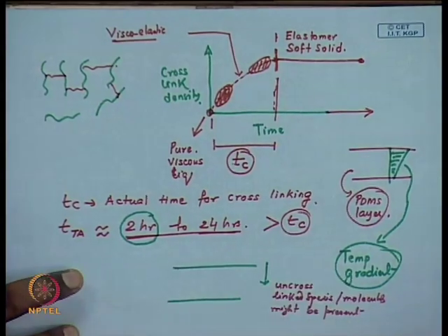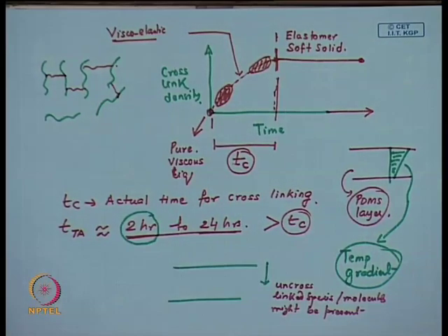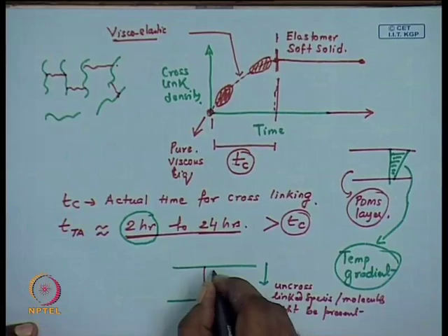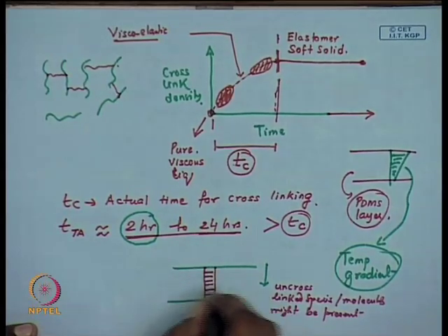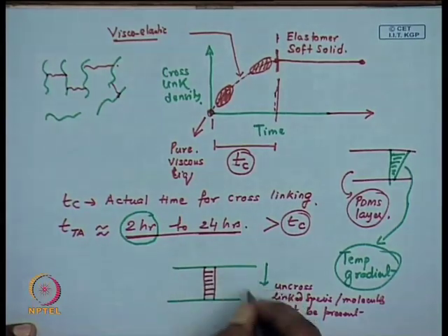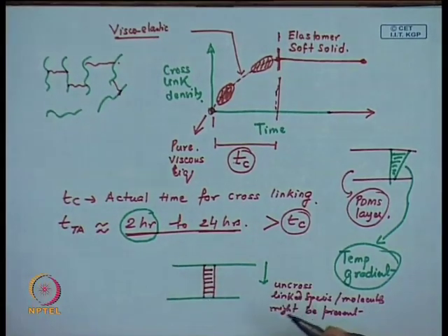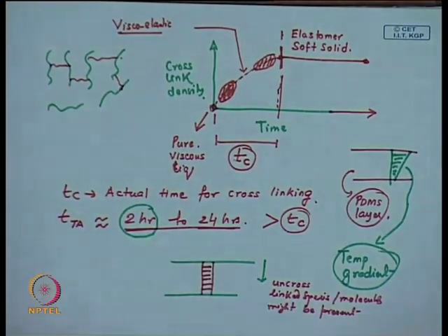In contrast, this is a simple heat transfer problem, if you heat it for a prolonged duration, probably you will have a much flatter profile, and the cross linking density variation along the depth of the film will be less, which is of course a setting that you would like to have.